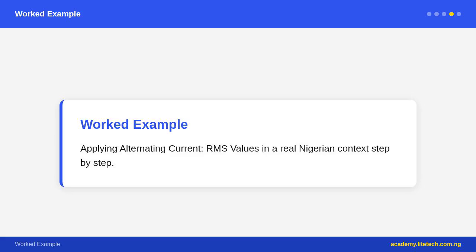Rectification is the conversion of AC to DC, required because most electronic devices, computers, mobile phones, radios, need DC. A diode is a semiconductor device that allows current to flow in only one direction, from anode to cathode, when forward biased. Half-wave rectification: one diode in the circuit, only the positive half of the AC cycle passes, the negative half is blocked. Output is pulsating DC, goes from 0 to V0 and back to 0, but never goes negative.